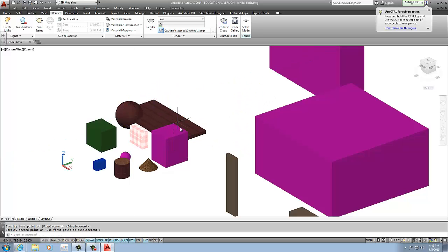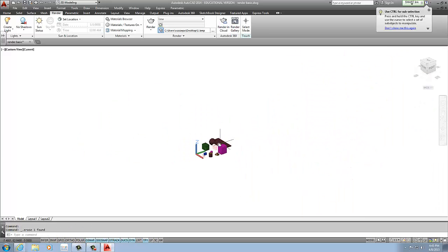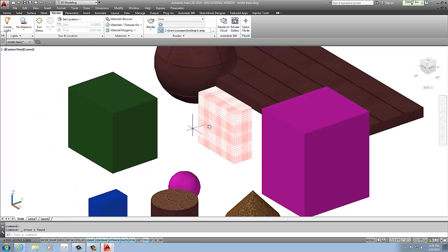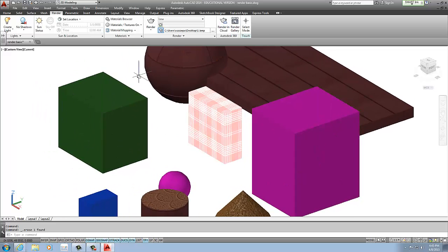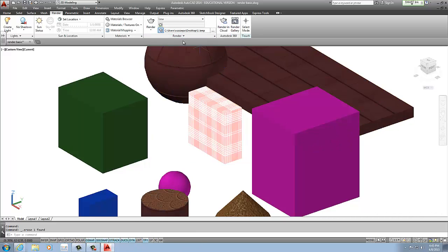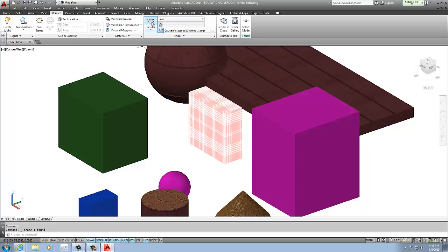next is move into our next major step. I'm going to delete some of these because that's just going to oversize my drawing. I zoom in so I can fit the entire object or objects. Now remember, I have these templates and this lower bottom that's covering the actual view, but when I do the render, it selects everything. Now to do the render, we have it set at low. Again, make sure it's either draft or low, and right next to it is the render.